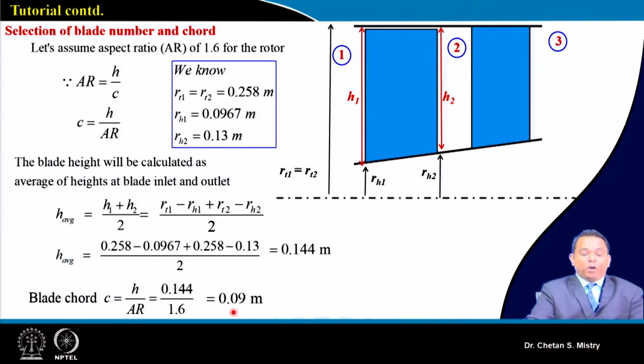Now many times when you go with this assumption, this number may come slightly on the lower side, and realize one thing: when we were discussing the contra-rotating fan design, we realized that part. What will happen is my chord will come very small. When the chord is small, that means you need to do a whole lot of diffusion with a small chord.